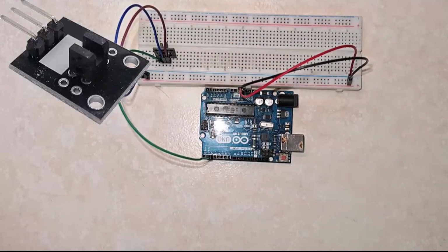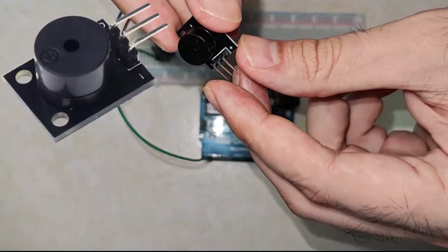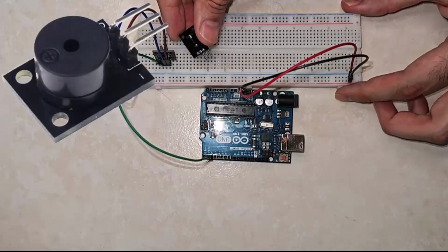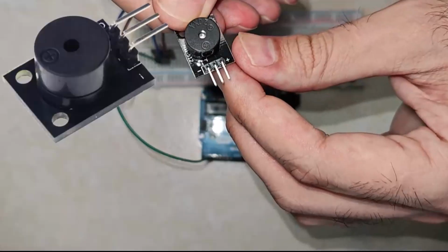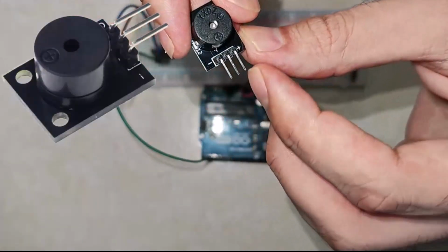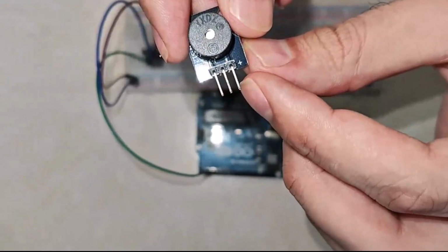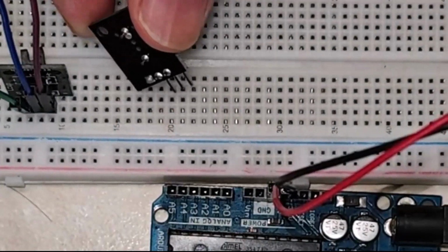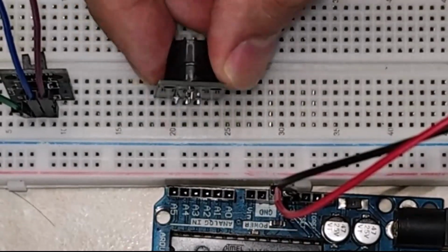The first thing that I'm going to add today is the buzzer module. But don't worry, if you don't have a buzzer module, you can use normal passive buzzers. My buzzer has 3 pins, but we don't work with the middle one, so we only need the GND and the plus. Plus is our signal pin. So I'm going to connect my buzzer like here.